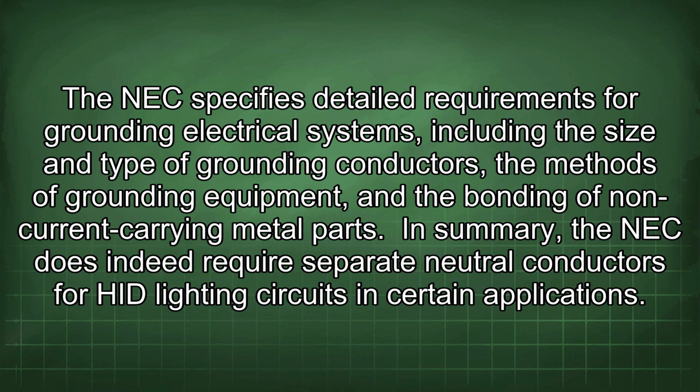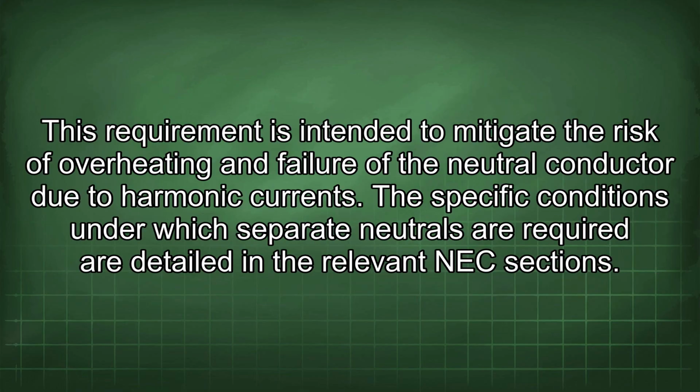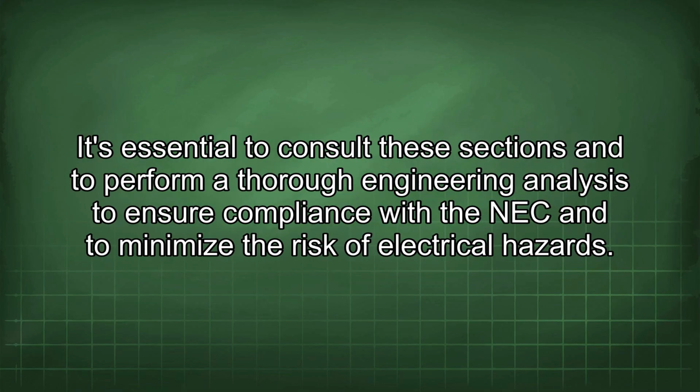In summary, the NEC does indeed require separate neutral conductors for HID lighting circuits in certain applications. This requirement is intended to mitigate the risk of overheating and failure of the neutral conductor due to harmonic currents. The specific conditions under which separate neutrals are required are detailed in the relevant NEC sections. It's essential to consult these sections and to perform a thorough engineering analysis to ensure compliance with the NEC and to minimize the risk of electrical hazards.